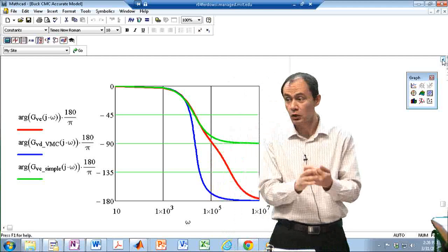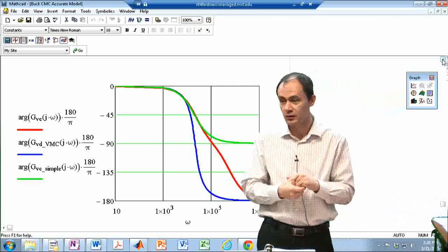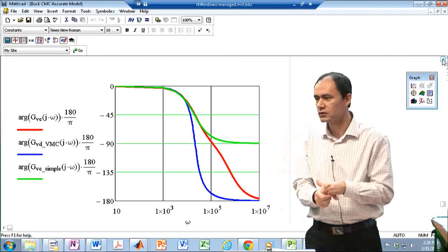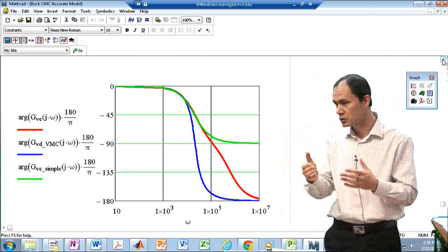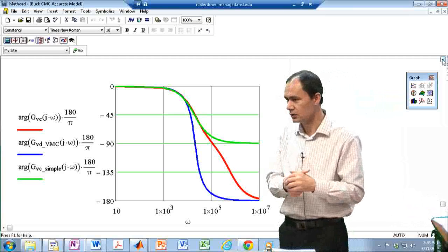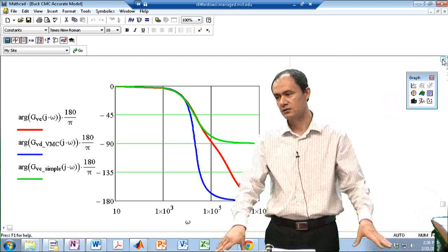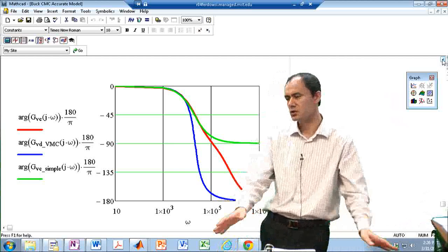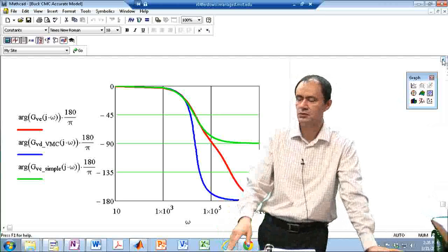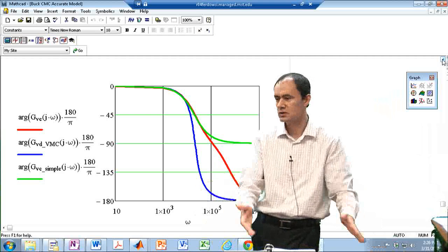Now, if they happen to be close to each other for a very particular design where, for instance, you don't care about the ripple in the output voltage, it's not a problem. You just have to be careful that you're not amplifying noise in your feedback loop, and that in terms of voltage compensation and phase margin, you're in the safe region. But usually that doesn't happen. Usually your corner frequency and your switching frequency are relatively far away from each other, like 5 times or 10 times.